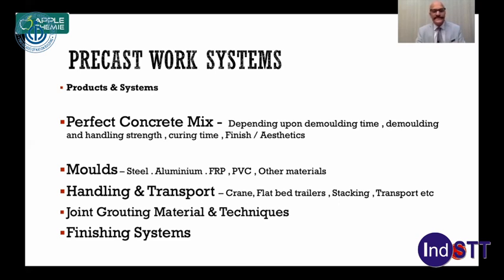As far as handling is concerned, you design concrete for initial handling, that is removing the concrete from the molds and putting it in the yard. That is the first stage. And the second stage is you handle it with a crane, put it in flatbed trailers, or transport it to the site, stack it there, and all those handling parameters. So that is how you do the handling system in precast works.